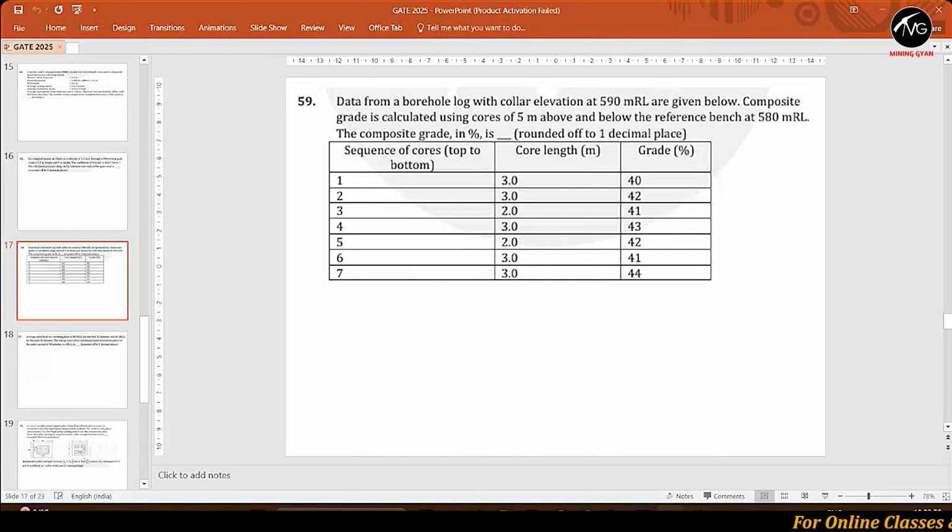So this is a question that is dependent on the Bieniawski pillar strength formula. Now, first of all, learn this question. So actually, what is happening in this question? Earlier there was an intact pillar of around 30-meter width. Then the depillaring started from the board and pillar, and that square pillar was divided into 4 square shaped stooks of equal size. So the strength would be compromised.